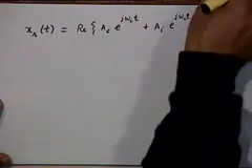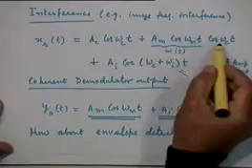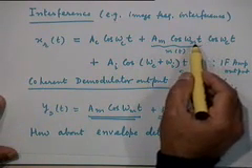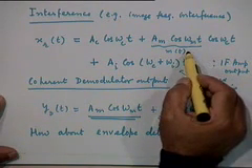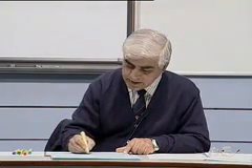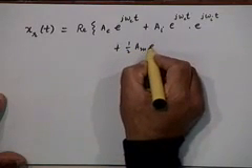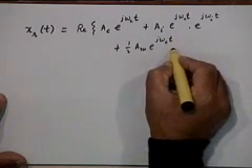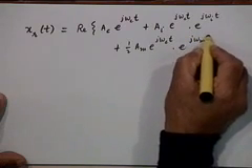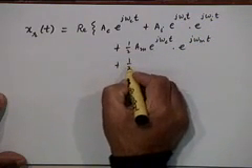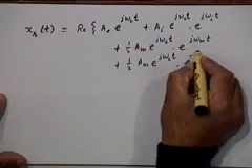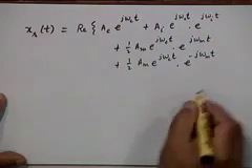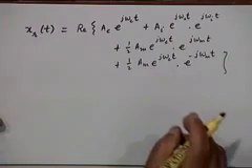And then there is a modulated component. There are two sidebands present here, one at frequency omega_c plus omega_m and the other at frequency omega_c minus omega_m. So what are the corresponding phasor components? This is plus half A_m e^(j omega_c t) into e^(j omega_m t), plus half A_m e^(j omega_c t) into e^(minus j omega_m t). So the real part of all this is that signal,